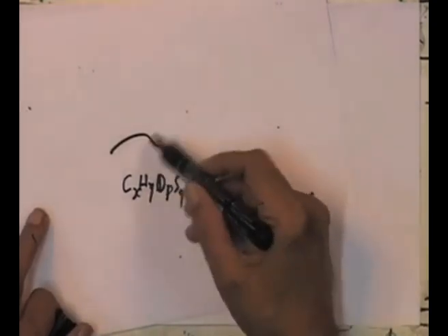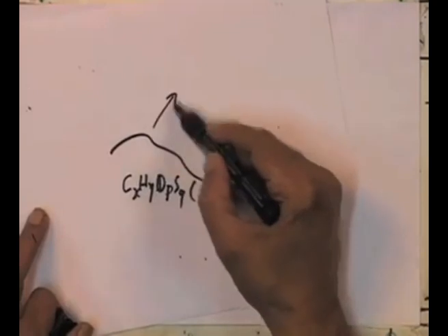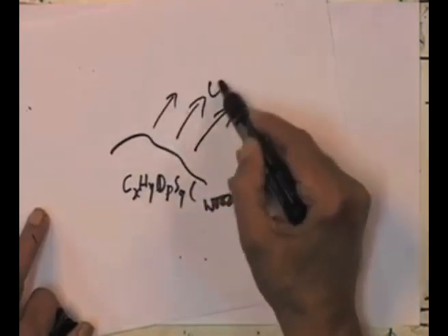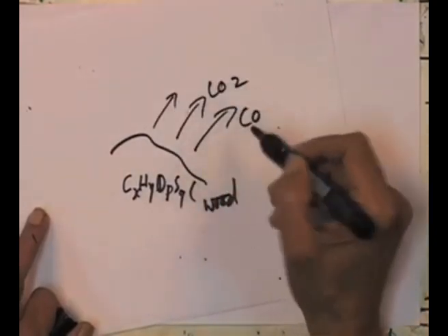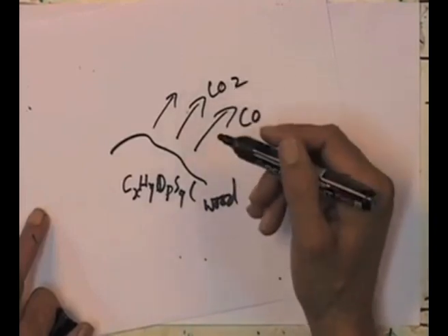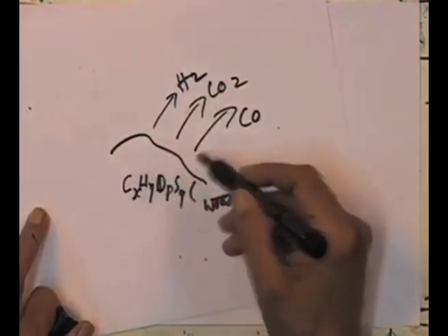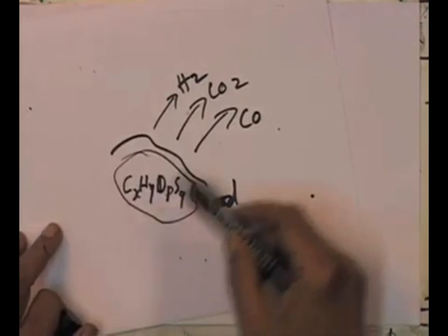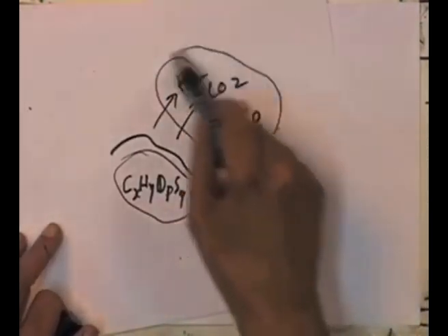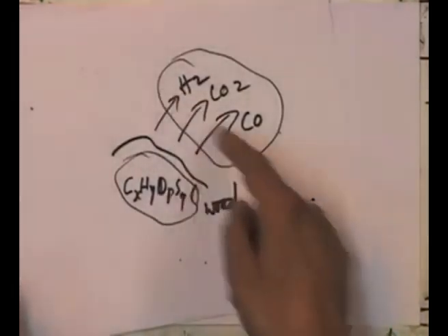And when the wood burns, for example, you will get all sorts of gases like CO2, CO or H2, depending on the temperature of the surface. So, the species involved inside the wood surface need not be the same as those involved in the considered phase, but the sum of the fluxes of these species and the sum of the fluxes of those species should be the same.